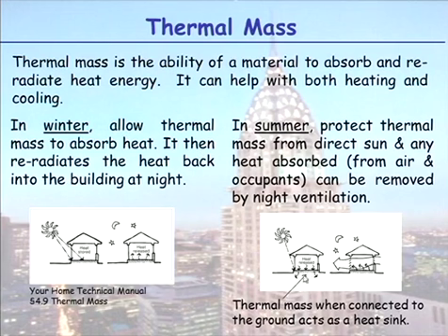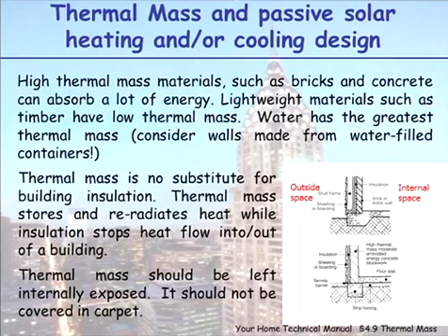a good sustainable design, not so much in terms of the concrete, but in terms of the fact that when connected to the ground, it also acts as a heat sink. So it can absorb the heat, and actually if the ground under is cooler, it can actually pull it out of a building. So high thermal mass materials such as bricks and concretes absorb a lot of energy.